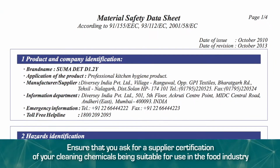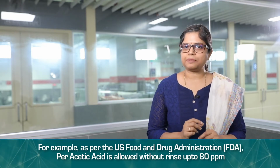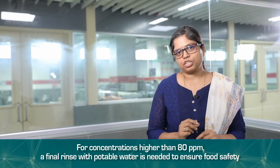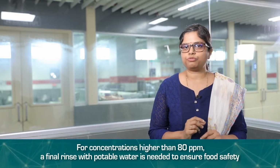How do you make sure that the cleaning chemicals, degreasers, disinfectants are safe for use near your food product? To do so, please ask your suppliers for a certification that the cleaning chemicals are suitable for use in your food industry. Do remember that all cleaning and disinfecting agents are prescribed for use at specific safe concentrations and these must be adhered to. For example, as per US FDA, peracetic acid may be used without a final rinse up to a concentration of 80 ppm. For concentrations higher than 80 ppm, a final rinse with potable water is necessary to ensure food safety.